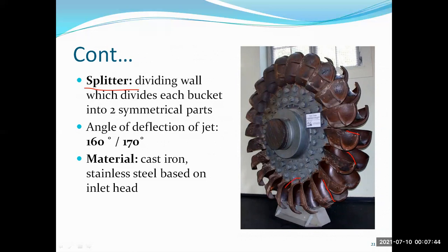It is designed in such a way that once water strikes the splitter, the jet will be deflected by an angle of 160 or 170 degrees. The buckets are made of cast iron or stainless steel, based on the inlet head.